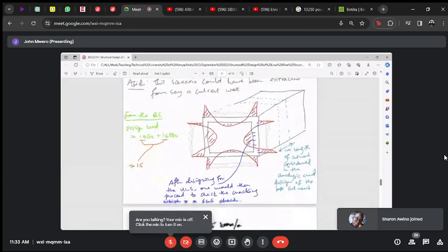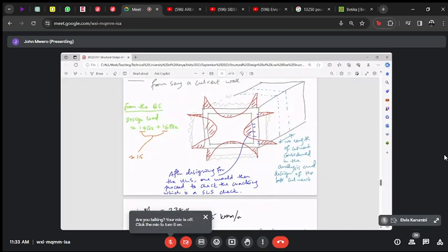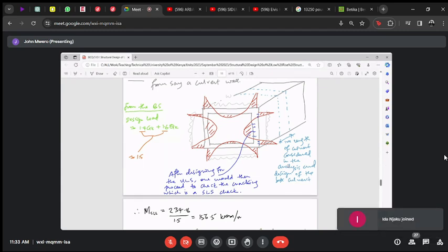So then I went ahead to try and explain where this particular example would have been extracted from. And hopefully in the next one session or two, we will look at how a box culvert is loaded. Basically, a box culvert is amongst the simplest forms of small bridges that you can find. So when a box culvert is loaded, what we sketched here in red is what would occur as bending moments. And I went ahead to then sketch for you on this 3D sketch where the cracking would occur. And that's where we would be interested to check the crack sizes.